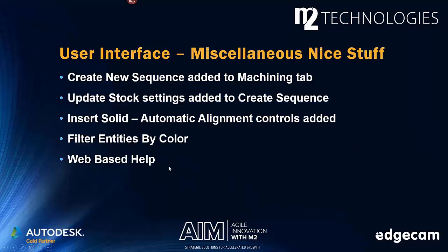Okay. A couple of other miscellaneous items. The create sequence command has been added to the machining tab. That command is typically on the setup tab, and it is the place that we often go to either create the first sequence in our part to complete the virtual CAM setup, and also to create additional secondary sequences that are relational to previous ones. So I've done the first side of the part, and now I want to flip it over and do the second side, all in the same model. And maybe then after that I want to send it out to a mill for secondary milling operations.